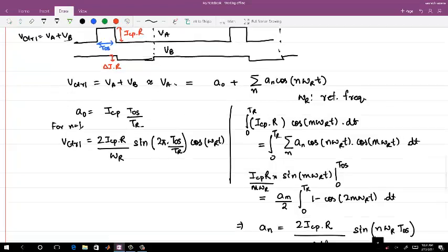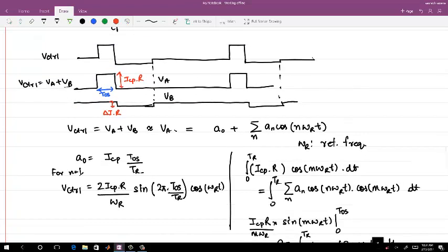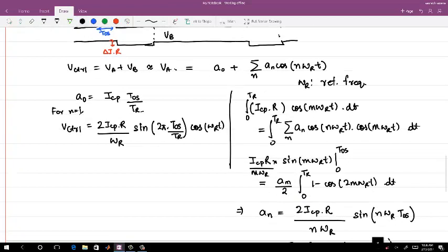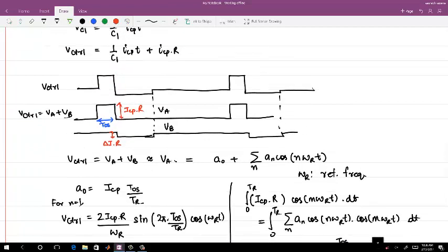Yeah, so you will find that the sine term will be 0 here. When you're only writing the Fourier series of this part, you can find that. And even if there is a sine term, if I take these two waves, the positive and the negative, VA plus VB, you will find a definite sine term, and then you can club it in some phase difference.